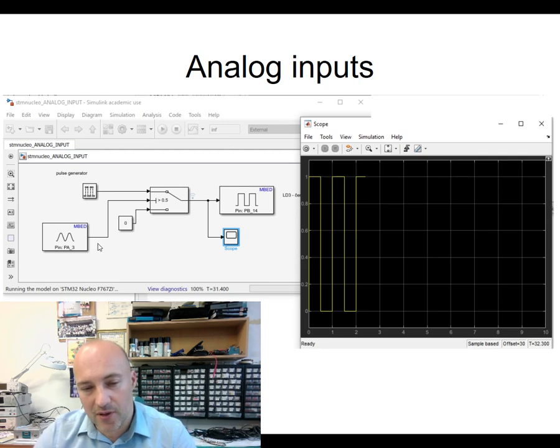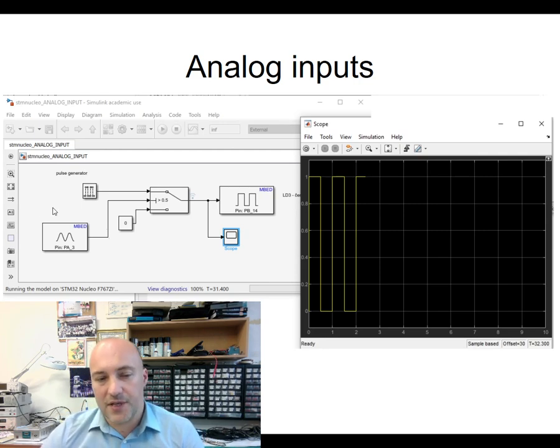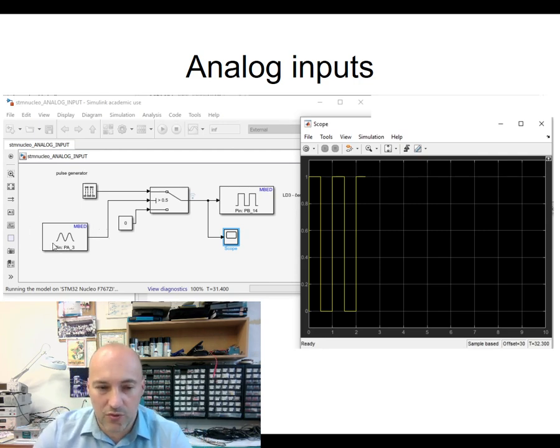So if, for example, the AD converter on this device can work from 0 to 3.3 volts, then if you get 1, it means 3.3 volts. So if you want real volts here, you need to multiply that with a constant value that you need to calculate in advance. So that's one example that you have available in Moodle.